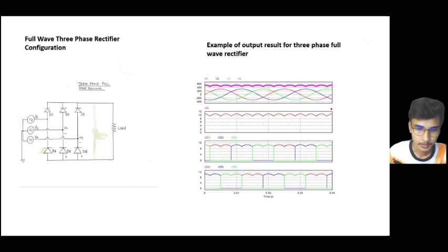For phase V3, it is the maximum voltage initially on the graph. From the example of the graph below, for the positive half cycle at the initial condition, from phase 0 until it reaches 30 degrees, V3 is the largest. V3 flows to D3, up through D5 and flows back to the V2 phase voltage.